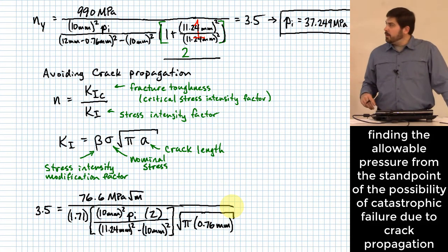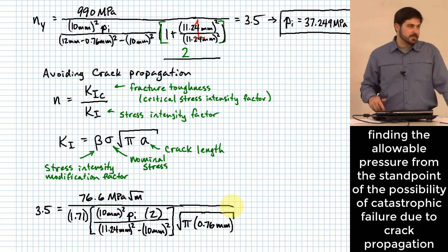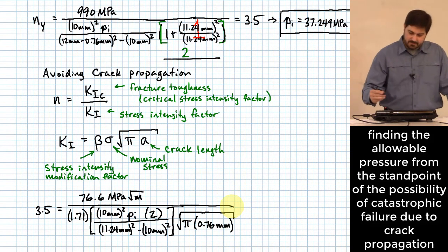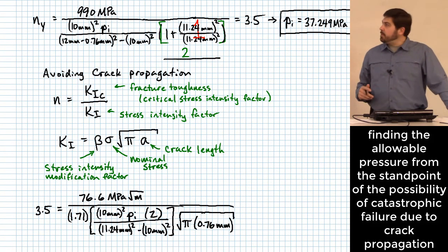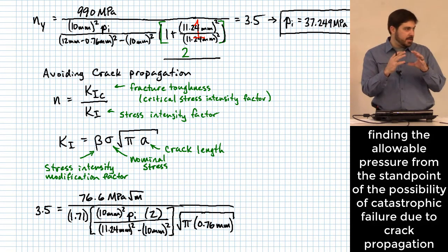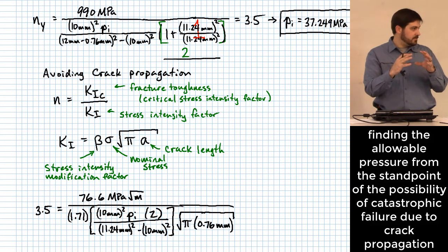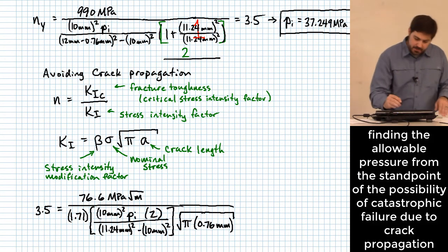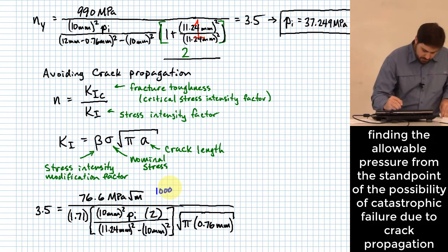Okay. Now there's one little tip I need to give you here. Right now in the numerator I've got this factor of square root of meters. In the denominator I have another factor that is going to have square root of millimeters. How do I make those units jive with each other? Well, keep in mind you can always take powers of the number 1 and it doesn't change what that is. One way of writing the number 1 is with 1,000 millimeters per meter.